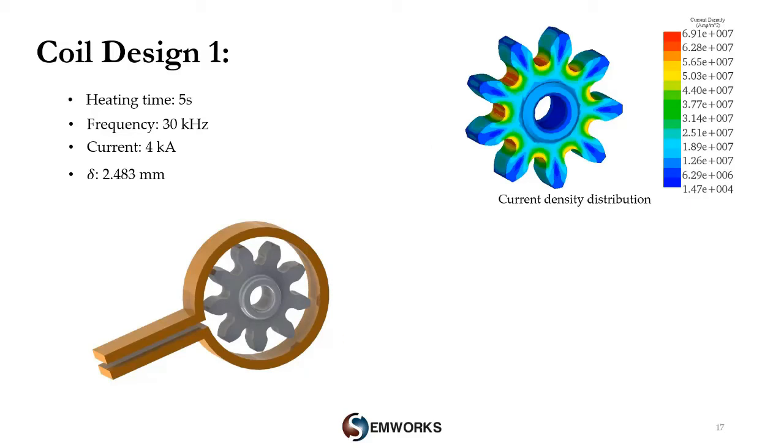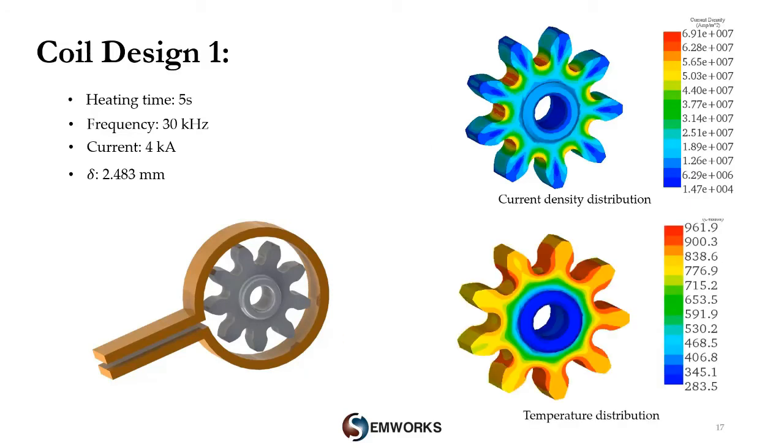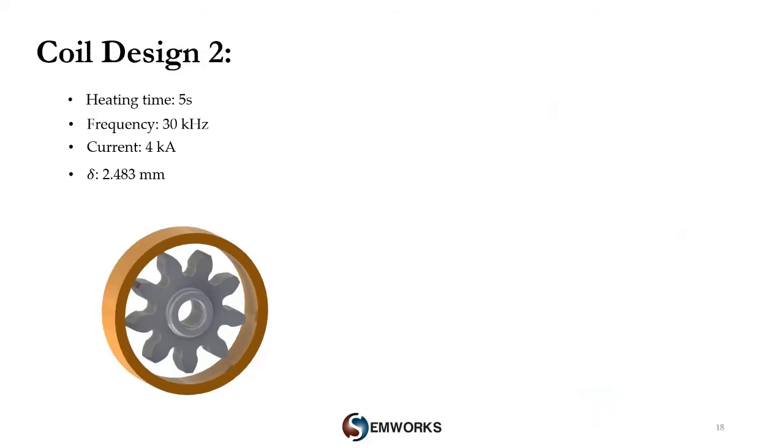But what about the temperature? As you can see from the following temperature distribution, heat is not symmetrically distributed, essentially around the teeth region, even if the desirable temperature rates are attained. So after being quenched, the hardening won't be uniform either. Then this is not good enough.